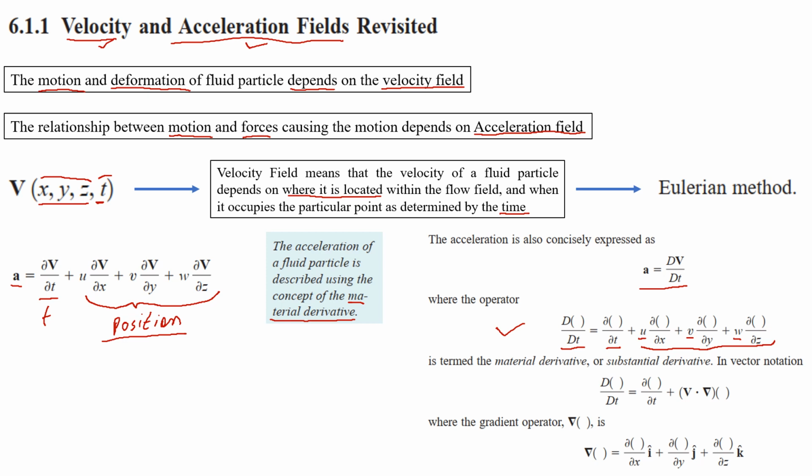So if you are studying the temperature here, you need to have the velocity field, the XYZ components of your velocity, to see that change with respect to position and with respect to time. This was the more generalized form of our material derivative equation. This is again the partial term, and this is the velocity vector, the u, v, w components of the velocity, and this is the del operator that contains all these partial terms.